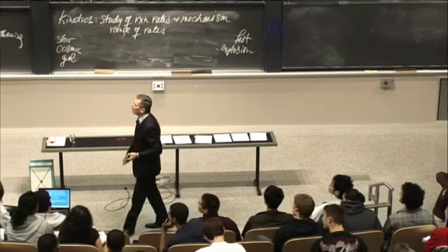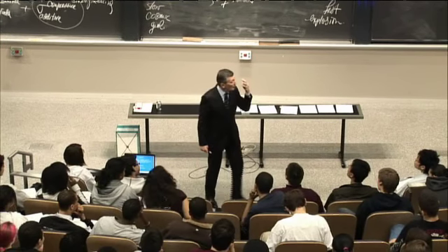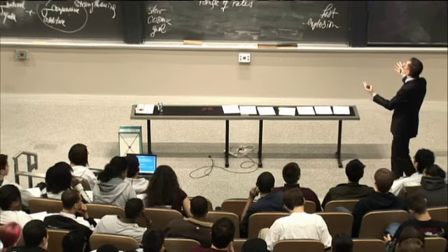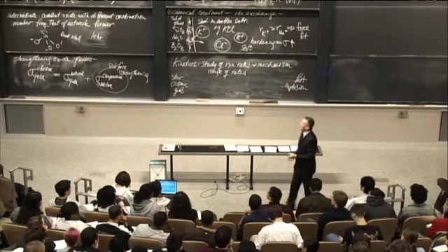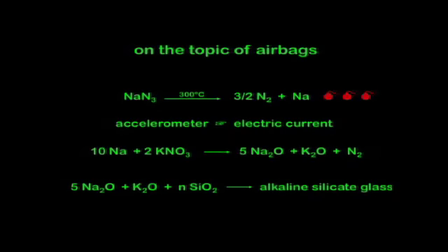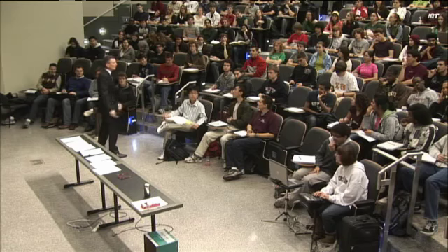All right? So now what? Well, do you want a mechanical, a Newtonian death, or a Coulombic death? I guess that's the question here. And so we're going to keep doing some chemistry here, and we're going to add silica. And what happens if we add silica to sodium oxide, potassium oxide? Well, that's a network former. These are network modifiers that make an alkaline silicate glass, and that's okay because we put food and beverages in alkaline silicate glasses. So everybody's happy.